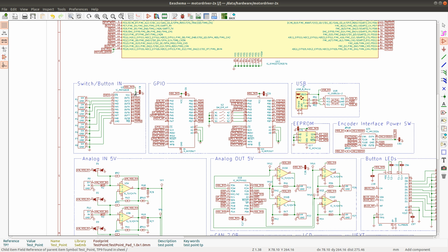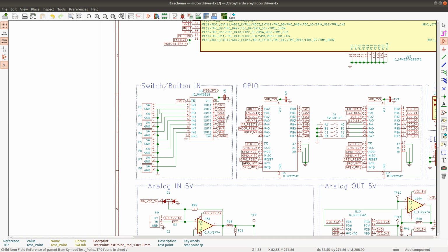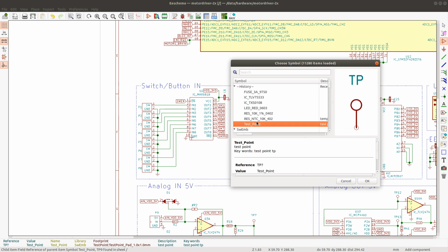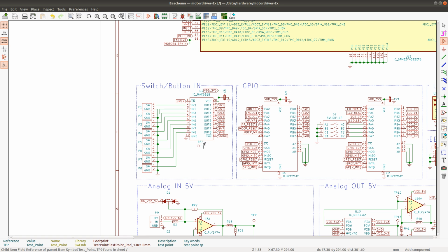We got the switches here, but I think that, kind of knowing that we have signals on the outputs here, I think that would be useful because this chip is going to be doing debouncing. So it would be helpful to see the delay that the signal has here because we cannot read it out fast enough to be able to see the delay. So let's put some test points here. Yeah, and on the RQ as well.